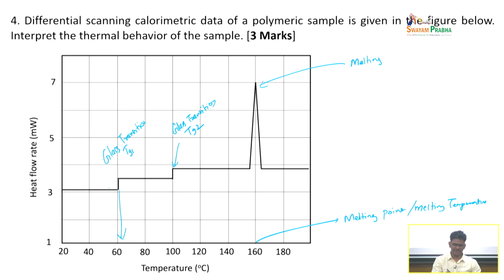Okay, this is just a hypothetical case, just to see that if you are presented with a DSC curve, you should be able to tell where melting is and where the glass transition is. So glass transition is a second order phase transition. Okay, so its signature is very delicate. The step change I have clearly shown, but in practice it may not be like this. It may actually have very shallow transitions, like this.